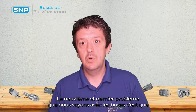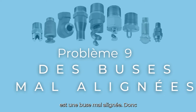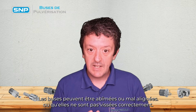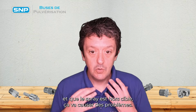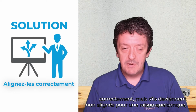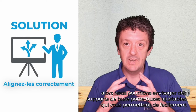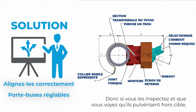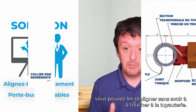The ninth and final problem we see with spray nozzles is poorly aligned nozzles. So maybe the nozzles get bashed or misaligned, or they're threaded incorrectly. And this, obviously, if they're spraying in the wrong direction and the spray's going off target, is going to cause problems. So the solution to this is, well, align them properly. But if they're becoming unaligned for whatever reason, then we may want to look at adjustable nozzle holders that allow you to easily realign the nozzles. So if you inspect them and see they're spraying off target, you can realign them without having to mess around with any of the pipework.